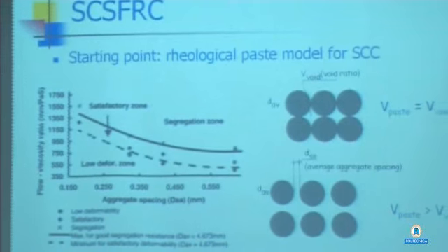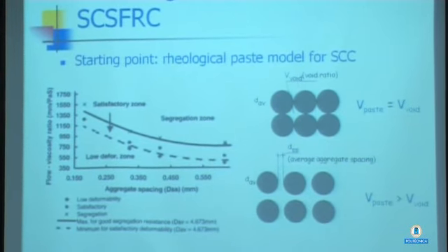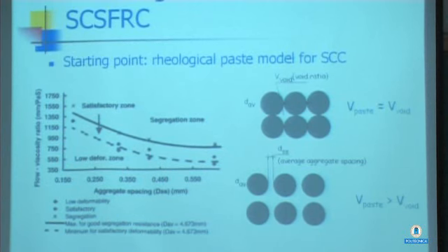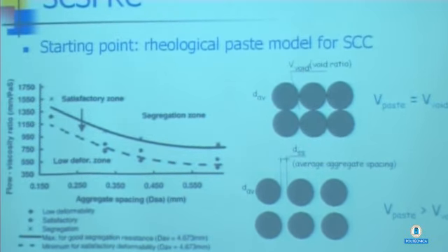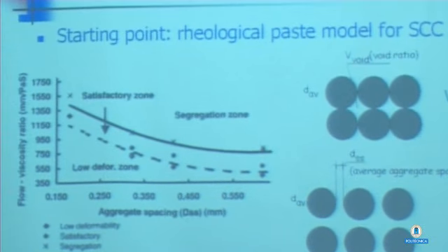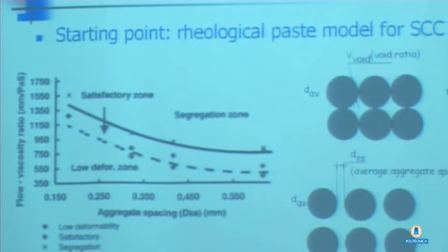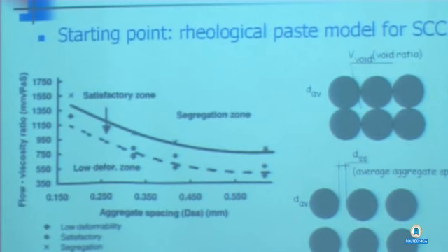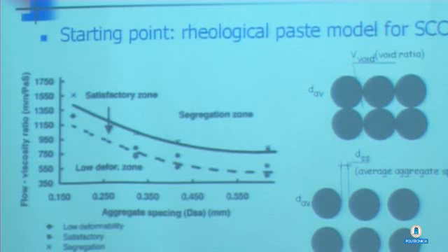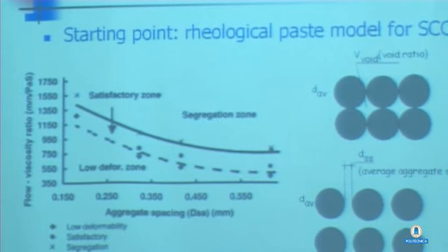Okay, what about the mix design methodology? Basically, we chose as a starting point a well-known, well-accepted mix design method for SCC, which is the Rheology of Paste model. The mix design methodology was developed at Northwestern University, and it consists of these concepts. We have a densely packed assemblage of aggregates. We can consider them as spheres, and they have a certain void fraction. So we need a minimum amount of paste which is just necessary to fill the voids, and in that case we have a very dense, very stiff suspension. All the paste in excess is responsible for the fluidity, for the deformability, for the self-compactability of the concrete.